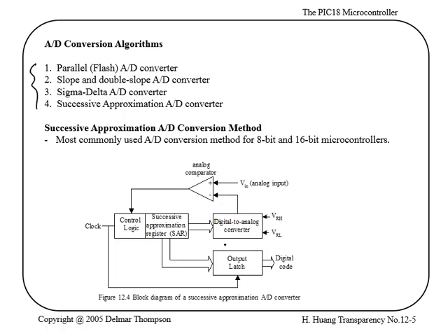Essentially the way that it works is, if you have a 10-bit value, and let's say the analog voltages you have are between 0 and 1 volt, then if this bit is 1, it means that your signal is greater than 0.5 volts. If it's 0, it means that it's less than 0.5 volts, right?